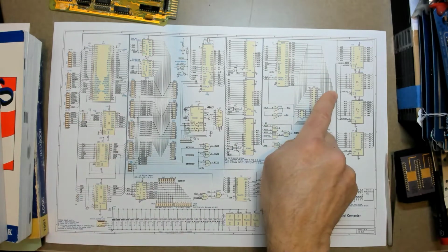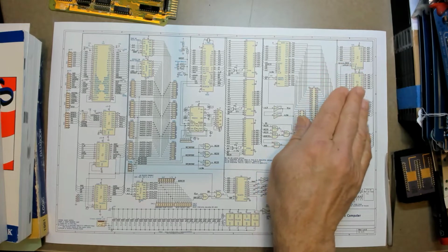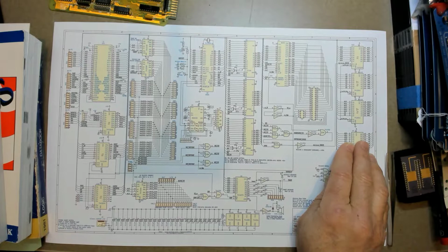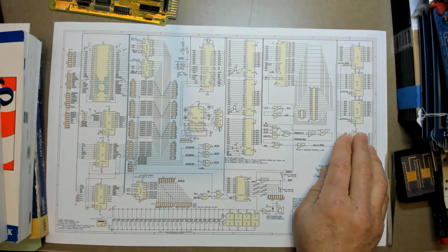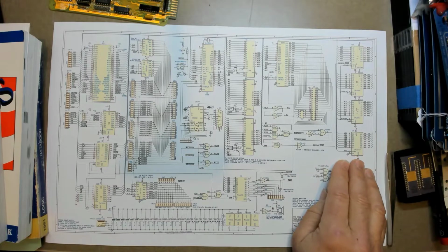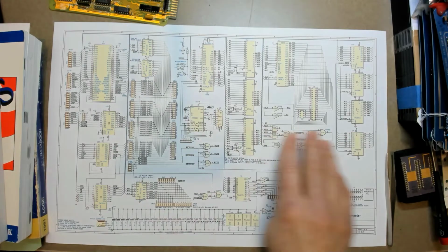Now over on the right hand side we have the drivers for the data byte and the 16-bit address. In the bottom right, this is an address latch. It's not actually part of the STD bus, but as we can see, it's required for the core design. It simply latches the low address byte off of the data bus when the ALE is strobed. So I should have called that out as part of the core design.